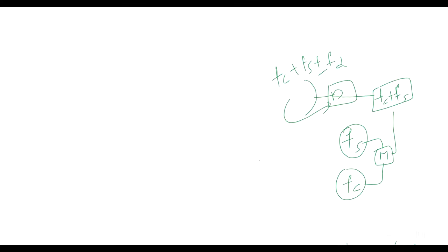Why are we using the delay line in the diagram? The delay line is used to introduce this time period dt. Delayed and undelayed signals serve as inputs to the subtractor. Here we have a subtractor in the diagram. To this subtractor, one input is after producing the delay. Another input is without applying the delay. These two are applied and we are getting the final display output.